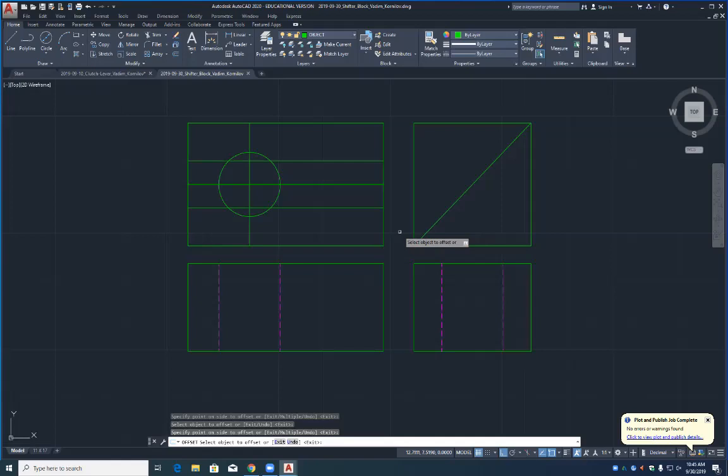So it could come down maybe to here. If you looked at it with a really close eye, you'll see little waves. Exactly. Let me show you what I'm trying to show you. If I go from here, I come up 1 inch off of the outside of the tolerance. The slot can vary a little bit, plus or minus 5 thousandths, right? That slot could move a little bit, because you put the 1 inch on the outside of the tolerance and the 1/2 inch on the inside of the tolerance. That's all I'm trying to show you.